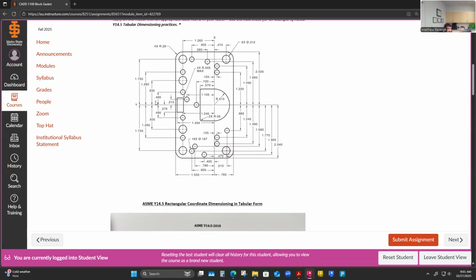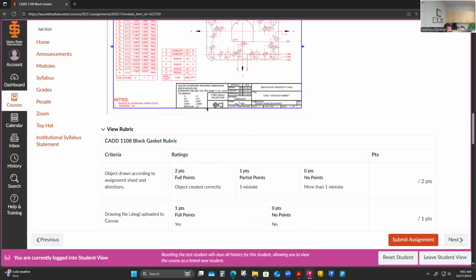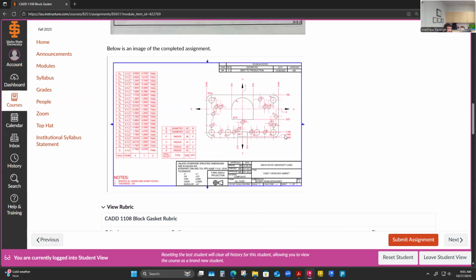So I'd probably just make a copy of my existing dimension style and make one out to 3 decimal places, rather than spot-changing all these and then using match properties. Then I'll carry a different style of dimensioning here.